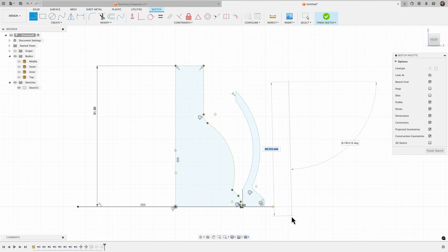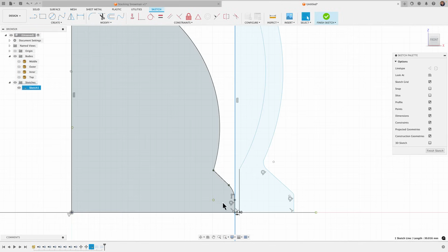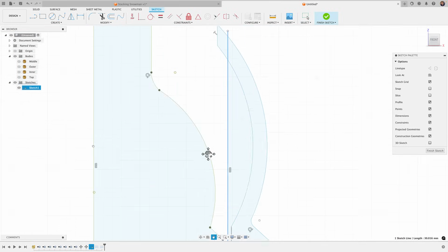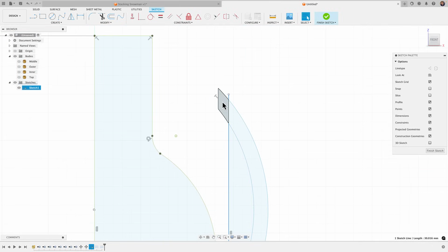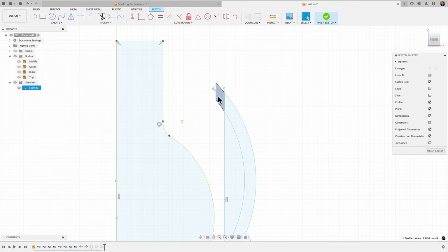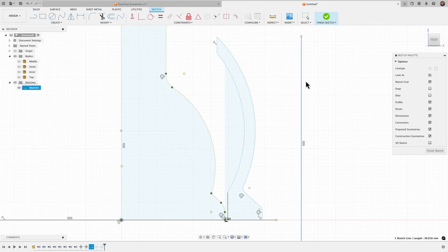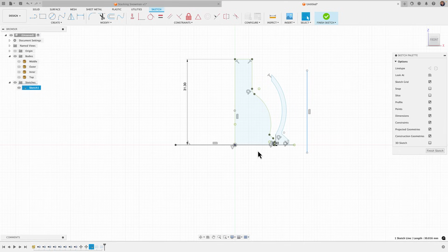draw a vertical line here, and I'm going to move it over. And so I'm going to line it up to the bottom here of that inner body, to the right to this edge. And so as this gets pulled up, what you want to make sure is that it is going to interfere with that middle portion here, because this is what's going to stop it from coming out. So you want to make sure you've got enough material here that this bottom section is going to hit it. Just make sure you have those 2 things in place, that clearance and that interference.